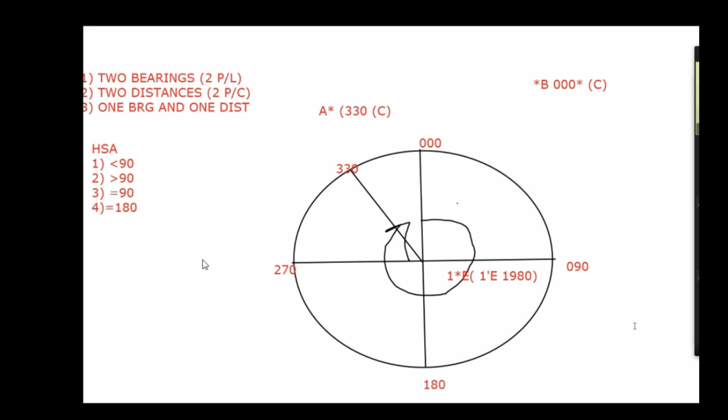And for that, various correctors are placed on the magnetic compass. If you go on top, you see the Flinders bars are there, and the spheres on the sides. If you open the compass binnacle part, you'll find the heeling error magnets and the vertical magnets are there. So Flinders bars are placed forward of the magnet, the spheres are placed in the athwartship direction, and for other correctors, there are some horizontal bars and vertical bars. So they are all correctors.